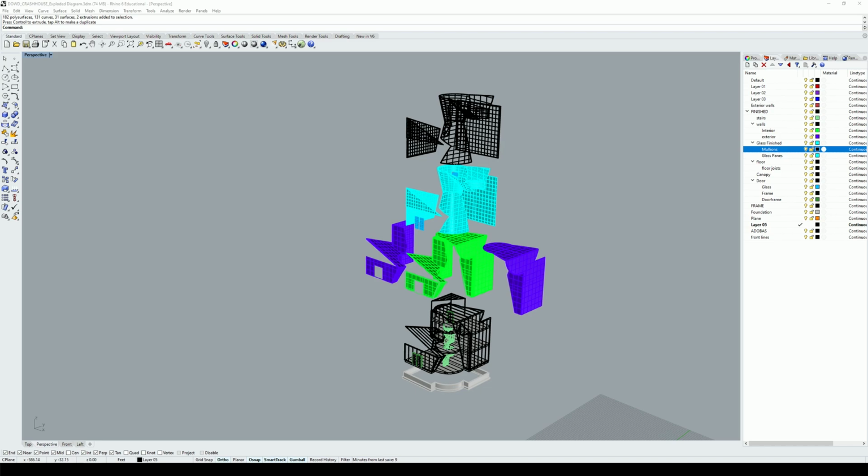Whereas in the case of our elevations, our plans, and our site plans, and our section drawings, those are all a 2D drawing, which means they don't have a vanishing point. They don't pinch. So you can actually make an axonometric is what it's called, or an isometric. Those are the scalable versions of this, or you can just make a perspectival. So I'll explain the difference, and then you can choose what you want to do.